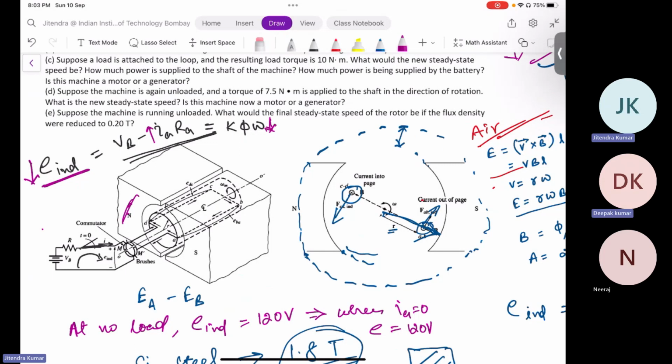Essentially, you make the field current zero or near zero. So no flux will be generated from the field coils. That is about field coils. I hope you understood, right? NI is the MMF that is generating flux, and you reduce it, and your flux will be reduced. Now, for the permanent magnet, how will you reduce this field?